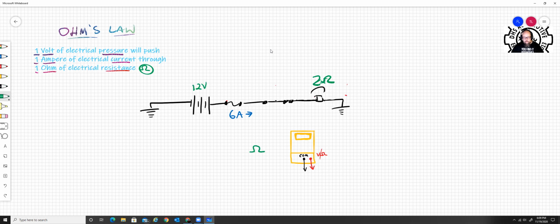Now, this goes for volts and ohms and amps. You need to find the practical range for what you're going to be measuring. Most meters today will auto range and set themselves up automatically for the most visually easy reading you could get. The meter you will see in the Electude modules makes you choose a range. So you kind of have to know a little bit about what you're looking at before you set it up, which is a little unfair because they don't set up a standard way to order the modules.